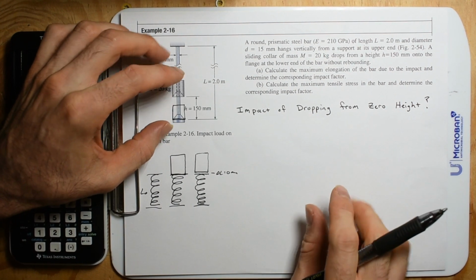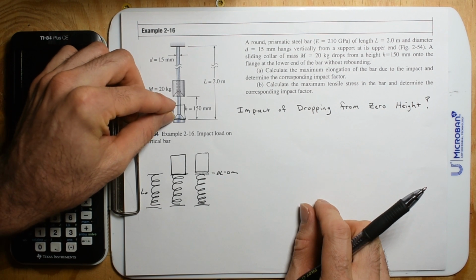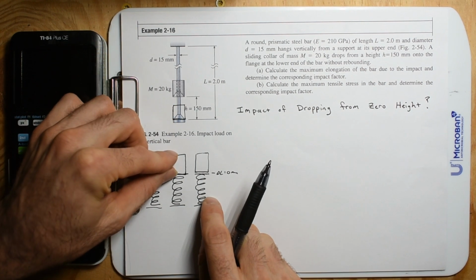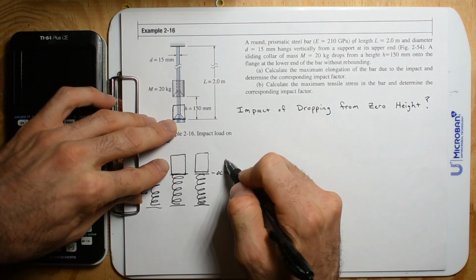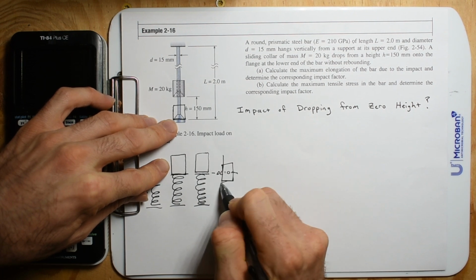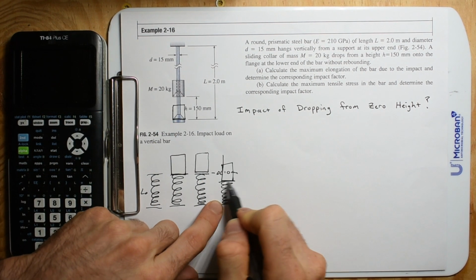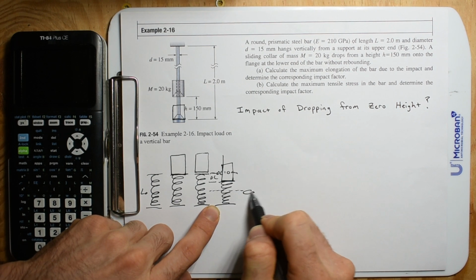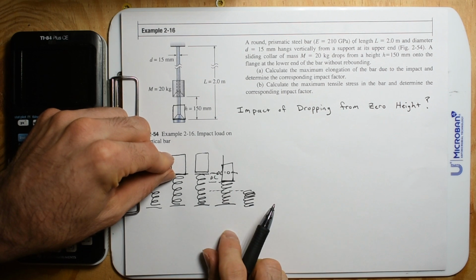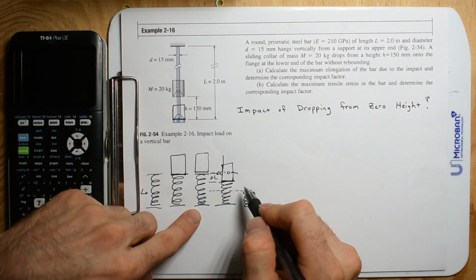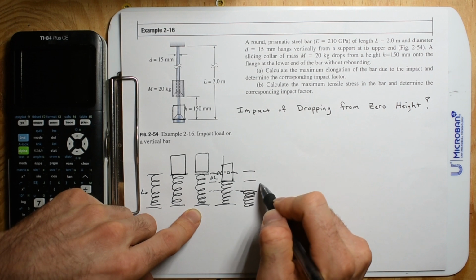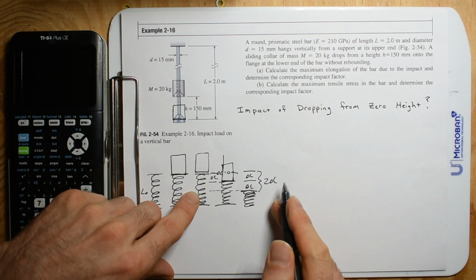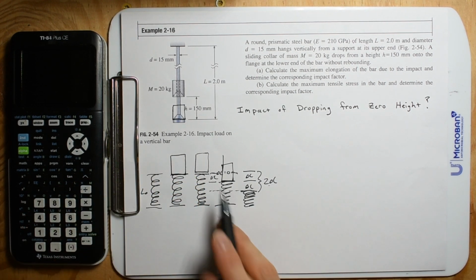Now, the straightforward approach is, if we hold it at that height and then very slowly relax it into the spring, we get this change in length. But the take-home message is, if we hold it right here and then just let go and impact it with its own weight, we're going to see that the change in length is 2 times this change in length. So we'll basically have a 2 times change in length type of scenario going on.